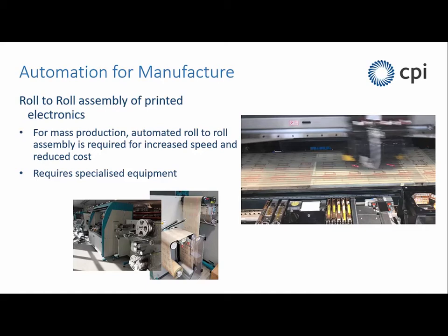The difference is that this is being done on a roll-to-roll continuous process. So we will have several hundred meters of circuit at one end of the machine, which you see down in the bottom left there. You see a cutout of it. I'll show you the equipment in more detail shortly. But it allows for continuous roll production of circuits.